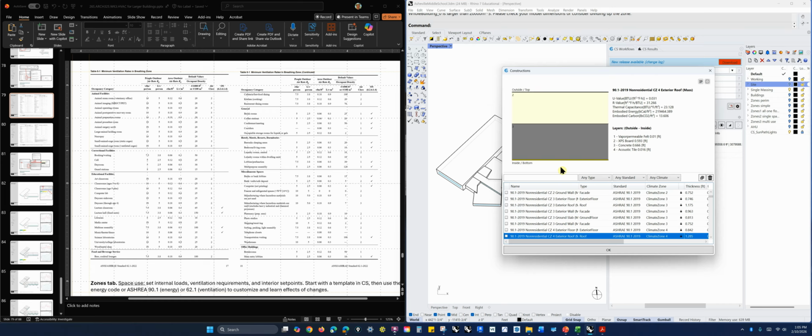If you go look in the code, you'll see that the R value, in this case for a commercial building with continuous insulation on the roof, is about R30. And so we've got R31 here. That's the minimum, it's R30. If we go look at the walls, it'll be similar. We can look it up in the code and it'll be reflected here. So we're just meeting the bare minimum of code with 90.1, it looks like in this case. Sometimes they may go higher for some reason.